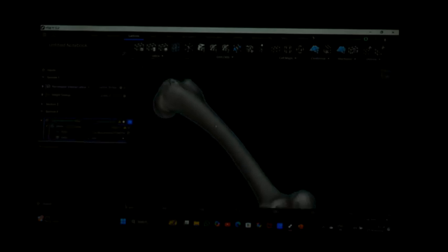You can see the icon again. I told you, icons. So this type of icon we can find here. I can keep this here. See, this is converting. Now the real problem is that previously we separated two bodies in the CAD geometry, like the middle portion. But here the problem is the bone is a scanned one, which means an STL file, so we cannot select the faces. We need to use Boolean operations here.